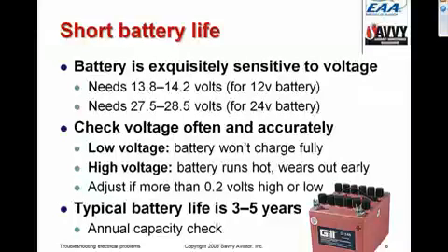By accurately, we need a digital meter that can read to the nearest tenth of a volt. Nowadays, most of our airplanes have something either on the panel or on the yoke that is capable of measuring bus voltage to the nearest tenth of a volt. An engine analyzer, a JPI or something like that, typically has a digital voltage readout.